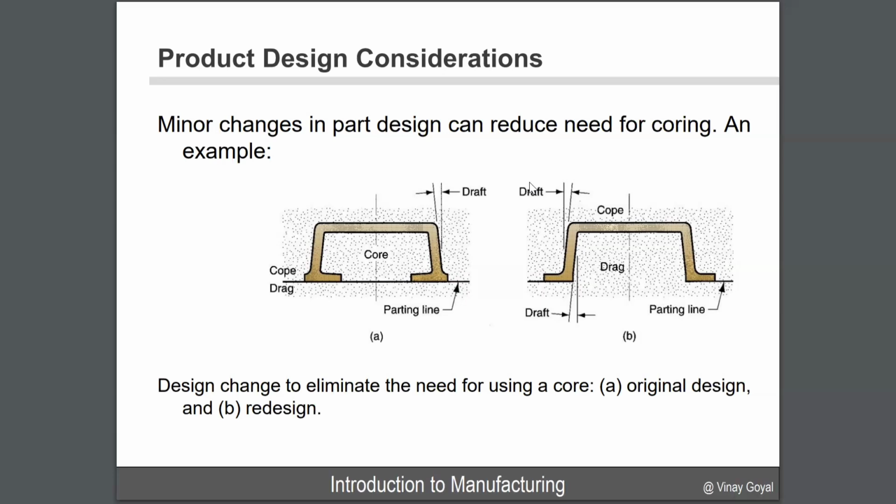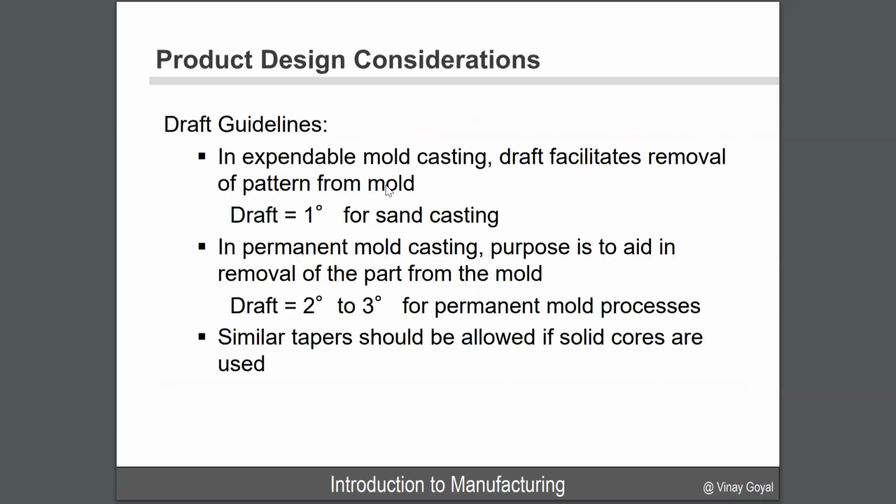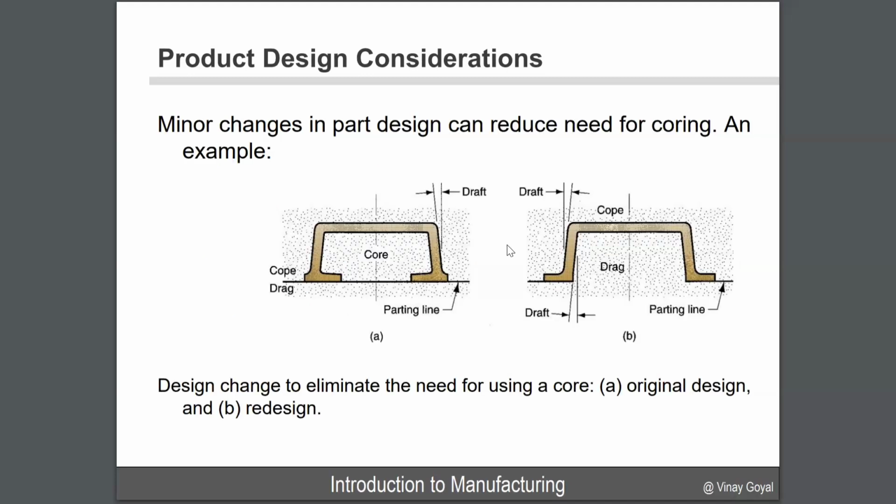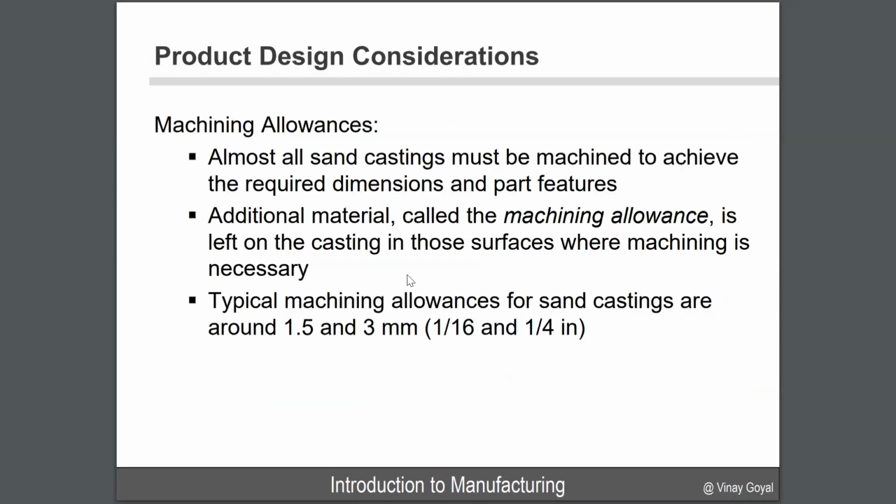By the way, if you don't know what draft means, I apologize, I should have explained it. That's typically covered in a CAD class. I don't know if that was covered in your classes, but draft is this angle here that we're talking about. So having some number of degrees of angle is very helpful. I apologize for not explaining that well. But you can see here that I needed a core, but if there's a way of not having to have that, that's beneficial.